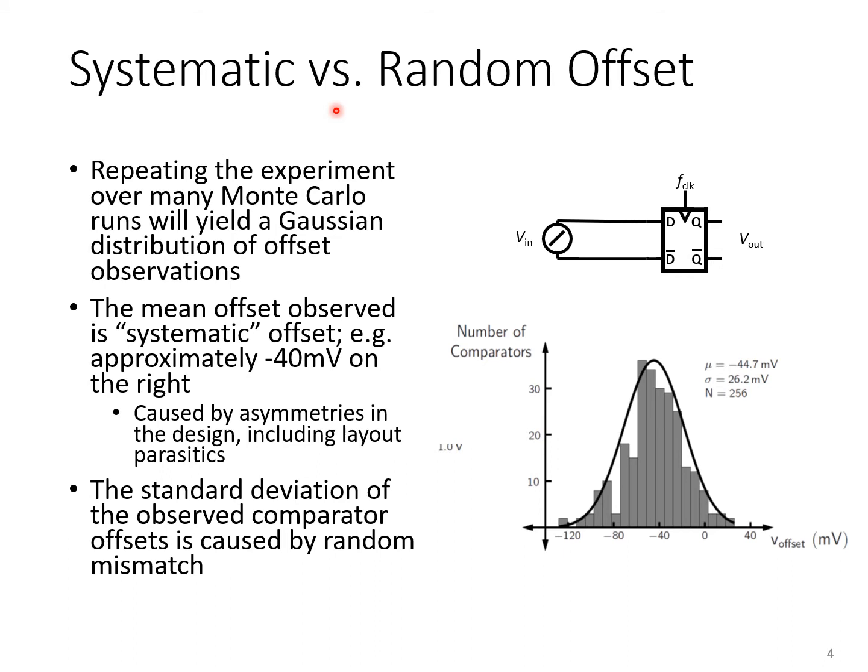So, for example, if you did a layout of the transistors in the circuit, and there's some tiny imbalance in the parasitic capacitances associated with the layout, then you could do a simulation on the extracted version of that layout, and you would see any systematic offset that arises in the latch. But in many cases, especially for well-designed layout, you would expect random variations to actually be larger.